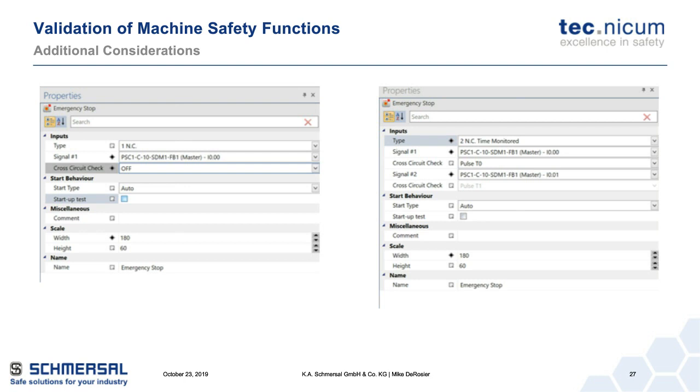And what we found in one particular case, where everything looked like it was working but introducing one single fault opened up the door, the machine kept on running. When we looked back, we verified that the machine was wired per the schematics, but when we looked at the installation instructions of the manufacturer's switches and controller, we found that the design was not correct per the installation instructions for the level they were trying to reach.